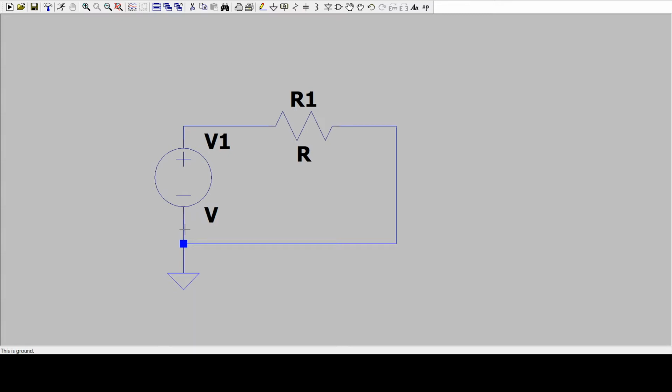Notice what happens here when there are multiple connections in SPICE. There forms a block. Like, so if there's more than a connection point, say here we have 2 connection points, if these are indeed connected within SPICE, you'll see a bluish block. If you're trying to connect 2 different terminals and you don't see this, that means that they are not connected or that you just have a singular connection, as is the case of this resistor. So something to keep in mind when you're troubleshooting your circuits.